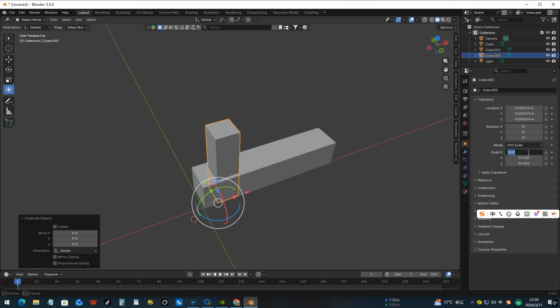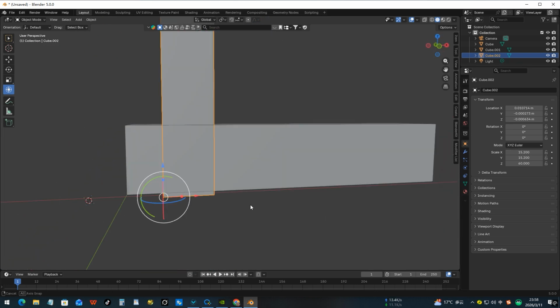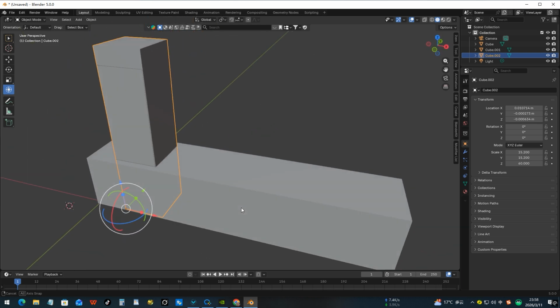Now, this cube, for tolerances, the best one that we are going to try first is 0.2 millimeters. That means you add 0.2 millimeters. So we write here 15.2 and 15.2. For this it doesn't really matter, but if you want you can write 60. Okay, so we have your cutter. This is the cutter. The cutter is gonna cut this object.